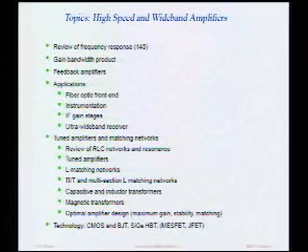Now, silicon germanium bipolar is a lot like the standard bipolar that you guys know and hopefully love, but silicon germanium transistors are actually HBTs, heterojunction bipolar transistors. From your perspective, the small signal model looks the same. The only difference is that RB is smaller and FT is higher, so it's nicer.